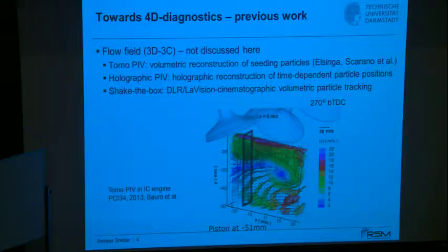But there have been other developments like holographic PIV, where you have a chance to reconstruct the three-dimensional particle position, from which you then take, in at least two shots, the volumetric velocity. Or more recent developments called shake the box, which is actually nothing else than volumetric particle tracking, but in a time-resolved way, where you then follow the particles along their path over multiple time steps. So I think this development clearly started in the fluid mechanics community and has been taken over partly into combustion diagnostics, where it has been seen as a very useful thing.